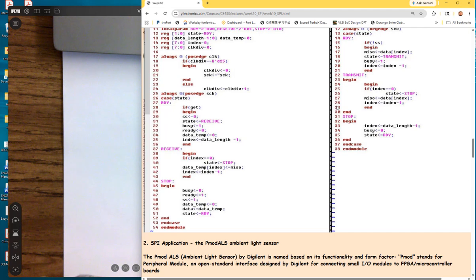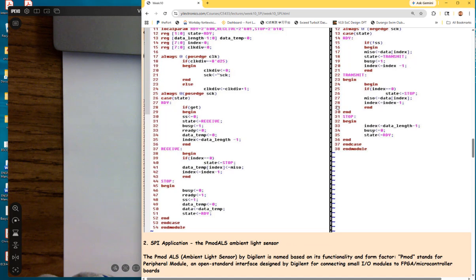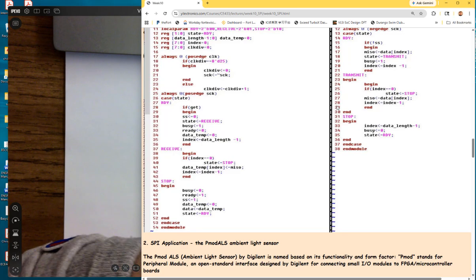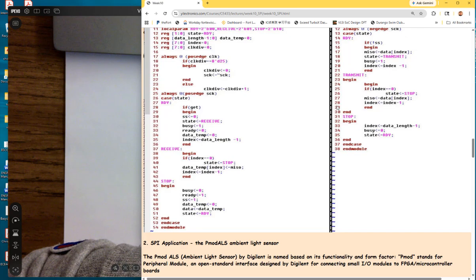What is the sampling frequency of your ADC? What's the range of it? 1 to 4 megahertz over 16. So 1 megahertz divided by 16 will be the lowest, and 4 megahertz divided by 16 will be the highest. Okay.